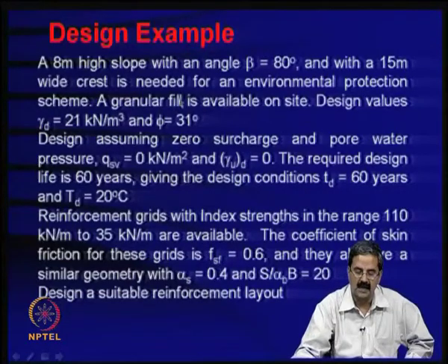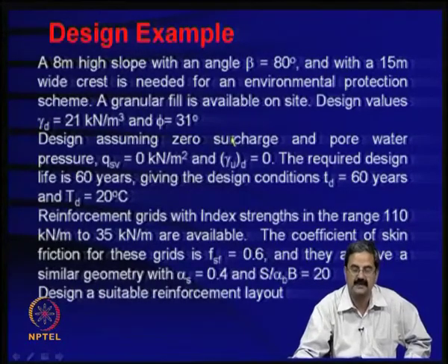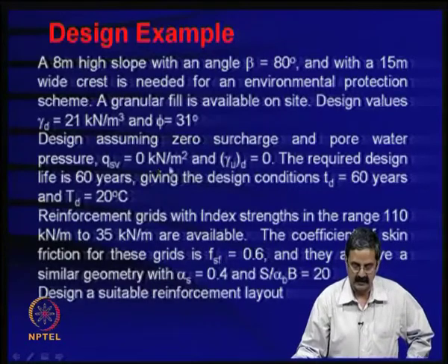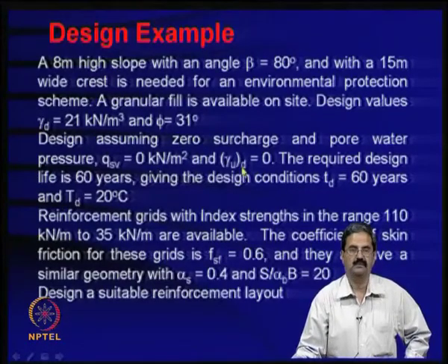And now you have a granular fill you are taking, and design values, okay, you may have lot of values for the same material, but you take 21 as a design value, friction angle as 31 degrees. Okay. Now, design assuming zero surcharge and pore pressure. Okay. So, surcharge is not there and pore pressure coefficient is also 0. These two things are very important actually.